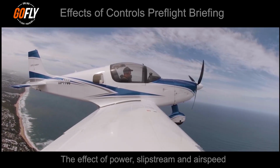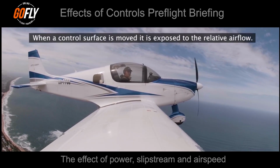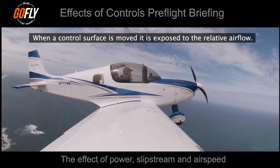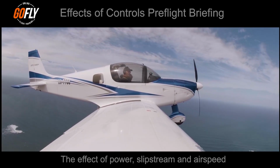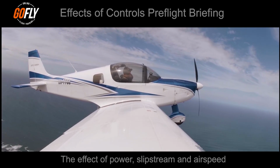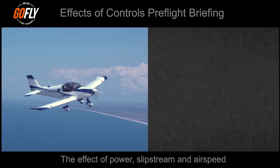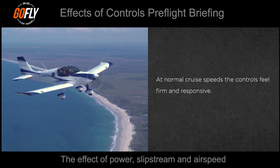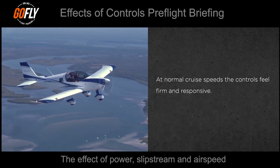The airflow that moves over the aircraft while it is flying through the air produces a force on the aircraft. When a control surface is deflected, the control surface is exposed to the airflow, and this produces a force against the control surface. This force can normally be felt through the control column. At normal cruise speeds, where we spend most of our time, the aircraft designers have designed the controls to feel firm and responsive.